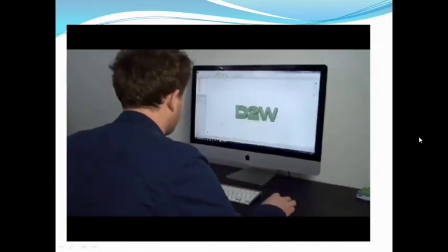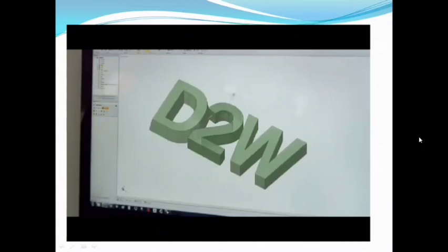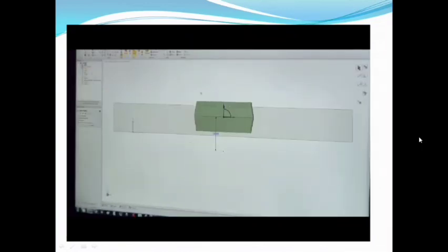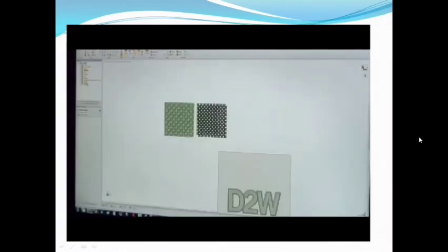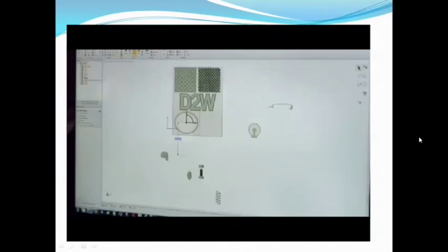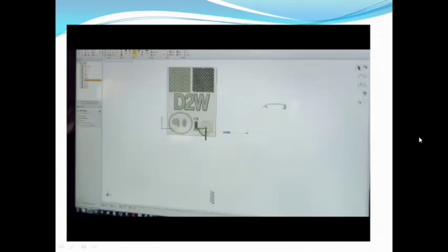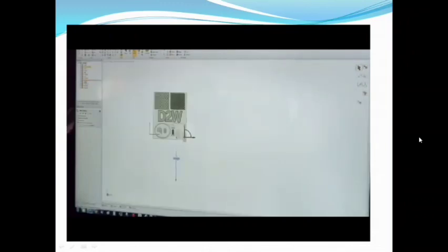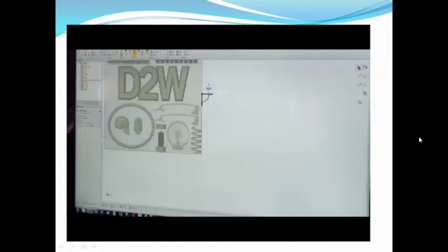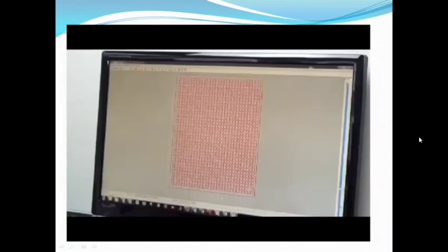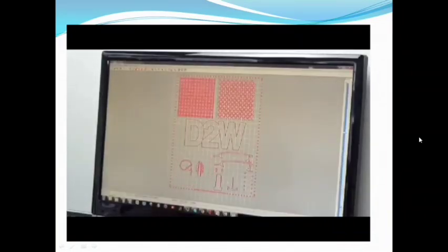The designed product is made using 3D CAD software with the proper dimensions. Then it is converted into STL format, and the data is sliced horizontally into thin cross-section layers and formatted into SLS machine data. After the completion of this, we come to the processing unit.